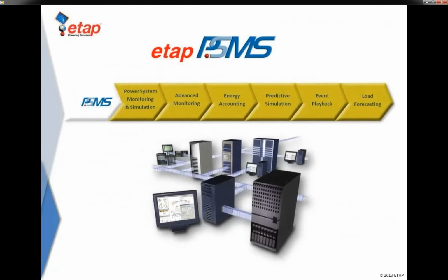ETAP PSMS is a multi-console client-server monitoring system. It provides a graphical representation of the ETAP one-line diagram. It allows you to historically archive data and retrieve it for display. You can display both electrical and non-electrical metering tags on the system, very similar to today's HMIs. It supports native OPC and native protocol interface layers to connect to intelligent devices already in the field, provides multi-access levels for operator support. It also allows you to provide asset information and power system performance calculations for stable operations.